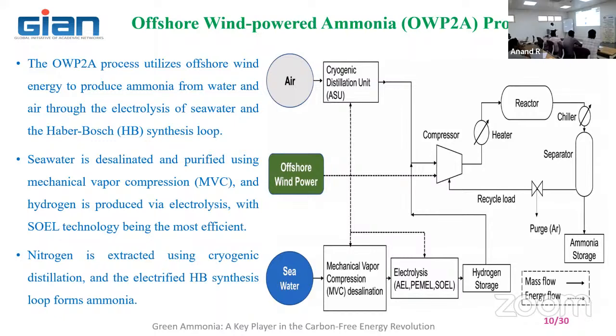Then we can go for either PSA, pressure swing adsorption, by providing mechanical energy to the PSA system to maintain the pressure difference. You can separate out nitrogen and oxygen, or the same way we discussed yesterday, separate the ammonia by using a deep freezer. Similarly, oxygen and nitrogen can be separated using a cryogenic low temperature distillation chamber, where each has its own boiling point. You can operate at a particular temperature and separate out the nitrogen. Then from the cryogenic distillation unit, nitrogen comes out.